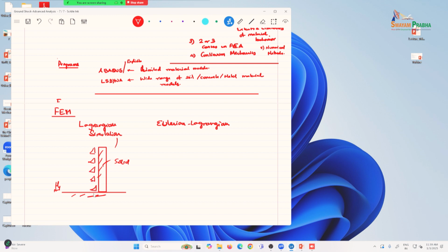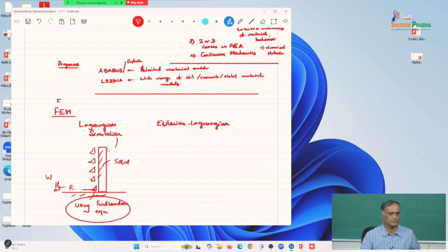These are blast pressures, using, let us say, the Friedlander equation. Internally, they will have methodologies by which the load gets converted. You will specify the distance, the location, heights and all that, and once you specify that, a simple analytical expression converts it, applies the load, solves it, right.